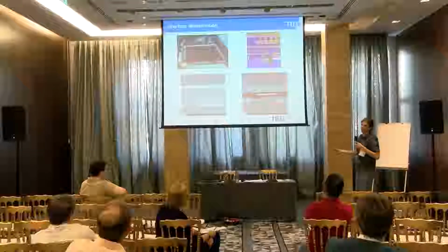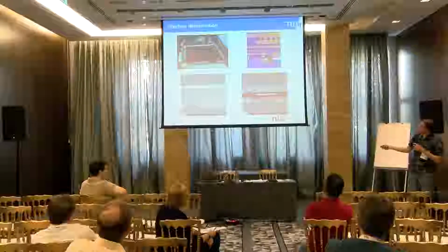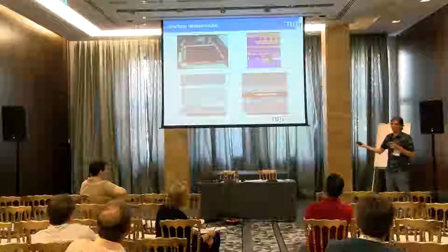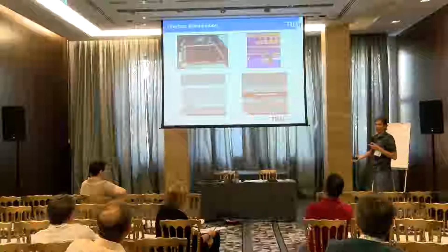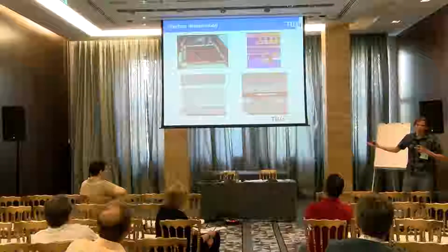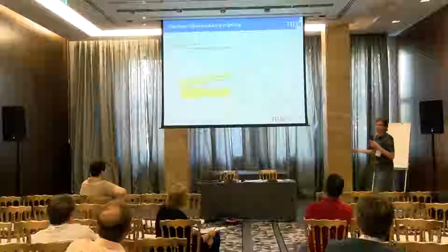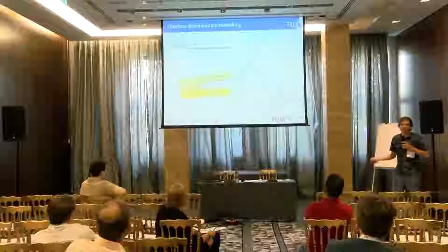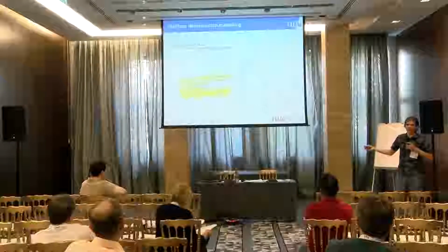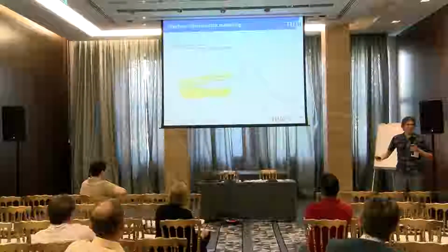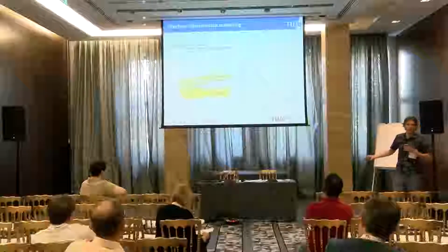But how do you then back out interface properties from this? Now, these look like really complex structures, so I'll show more a model system where we show that this works, the concept. But this is of course work ongoing. We want to identify an interface model, and typically what we would like to have is a cohesive zone model, because if you identify this, then you can immediately start using it for predictive modeling. So you can change the architecture and see if delamination still takes place.